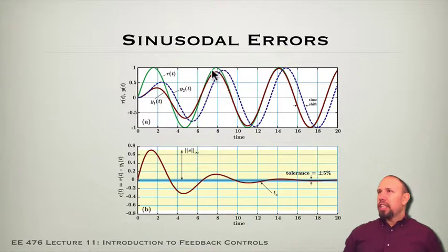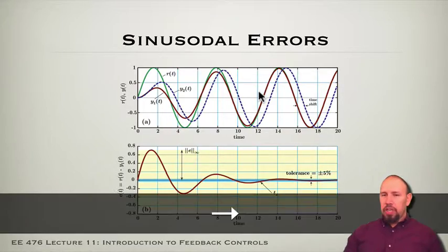Okay, or we could have a signal that eventually locks on to our reference signal and follows it after that. So if we were to take the difference between these two signals, we would actually get a signal that looks like this, and we could check that when we come within some tolerance of 0, then we can talk about settling time for our system. We can also talk about peak deviation of the two signals. So this is the peak deviation. Okay, and so these are some characteristics when you are trying to track a sinusoid. Those are some things to look at.